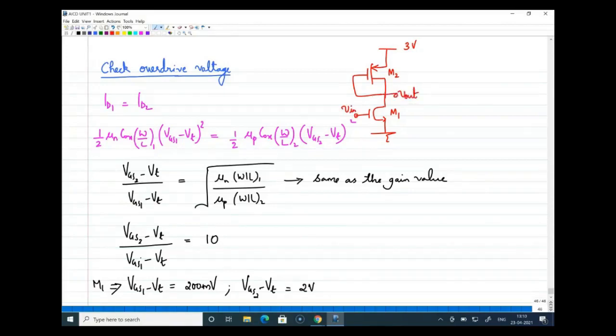So you can see the circuit diagram I have written in red on the screen, and the supply voltage is 3. The meaning of that is the total room. Generally we need to amplify a signal, so the entire room available is from 0 volt to 3. You'll be wondering what this new term, the entire room, is. From the supply rails, you can see the 3 volt supply positive, and this is ground. We generally call these the supply rails.